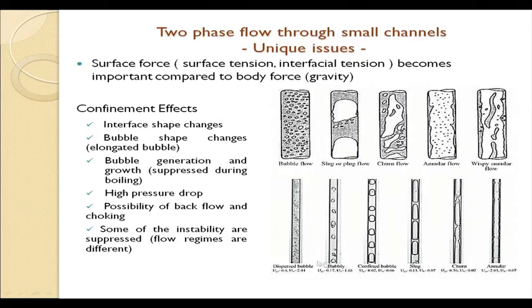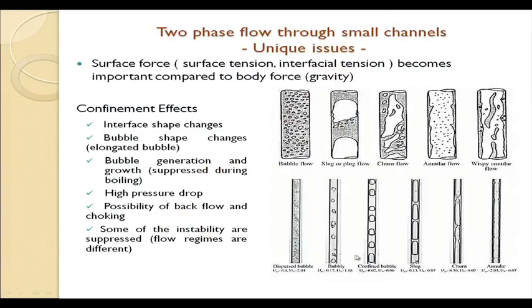In most of the regimes you find a periodic sort of appearance which characterizes the slug flow pattern. After this bubbly and confined bubbly, the bubbles start getting larger and assume the typical bullet shaped axisymmetric shape of Taylor bubbles. We call it the slug flow pattern.